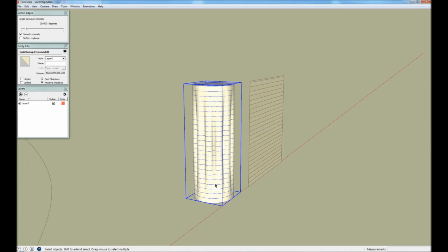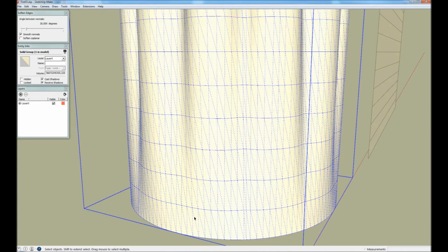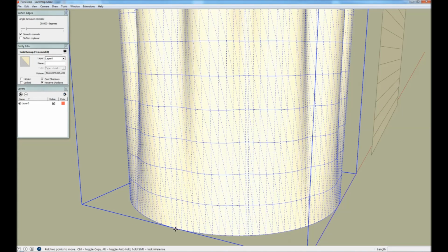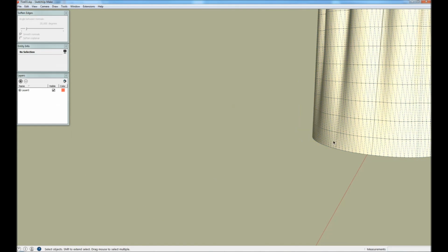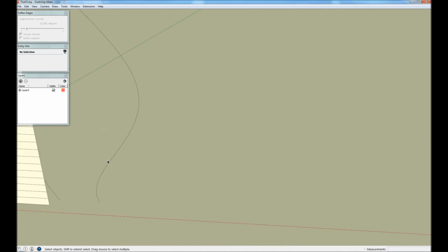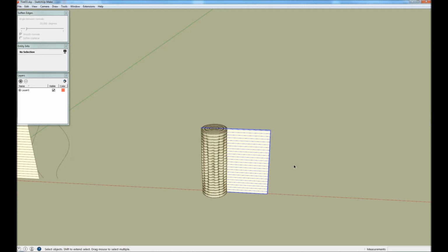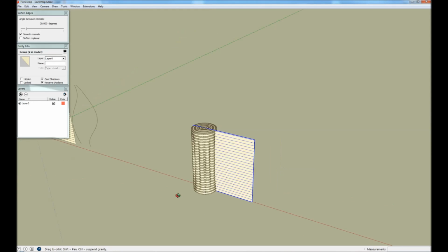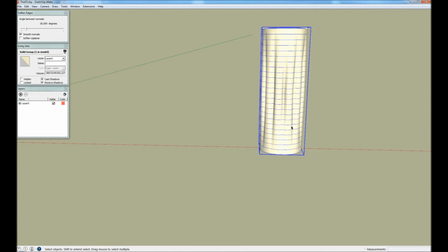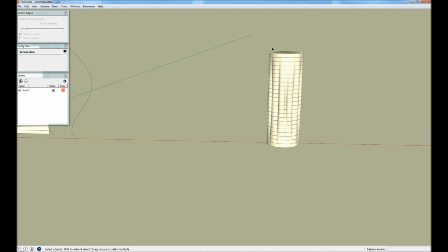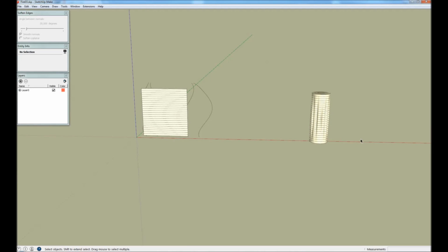So we're going to move the source geometry, and we grab the extreme point and add it to the corner. And then we just scale to the opposite extreme point. So this projection grid now has the exact same shape as the bounding box.